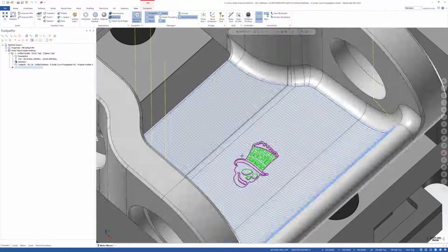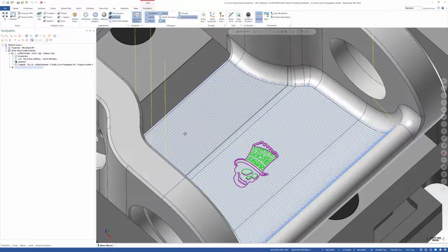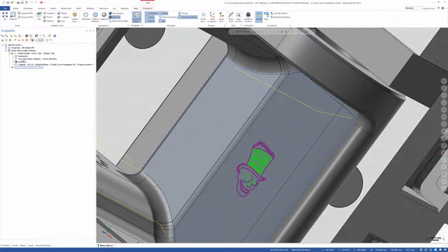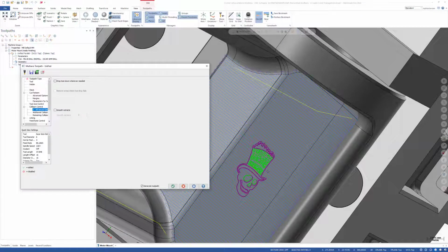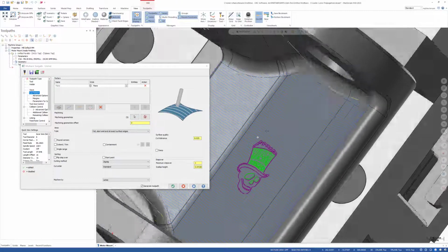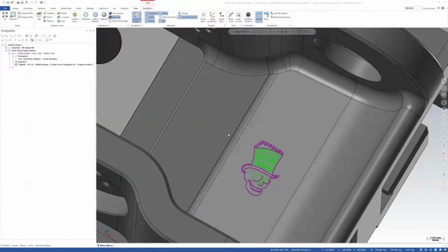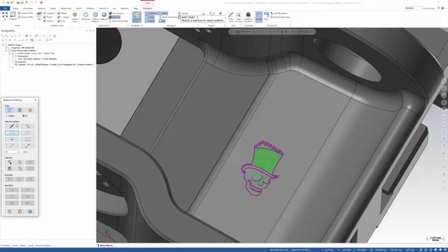And when I go back to 2022, not having this option is actually pretty painful. It's something that I've really gotten used to, and I think it's really, really powerful. So we've got a toolpath here, but it's kind of boring, kind of simple. So I believe our drive surfaces are already selected. Let's say instead of being parallel to a plane, we use a guide curve. And let's just select the outside of this logo as our guide curve.